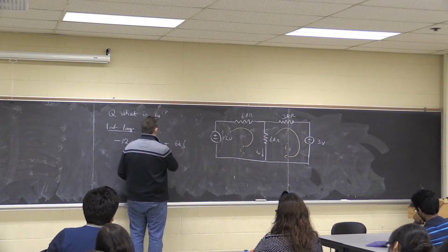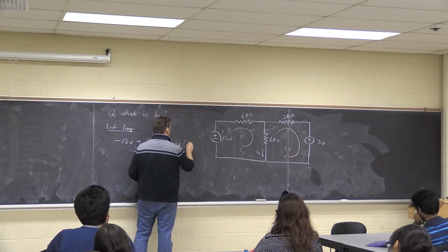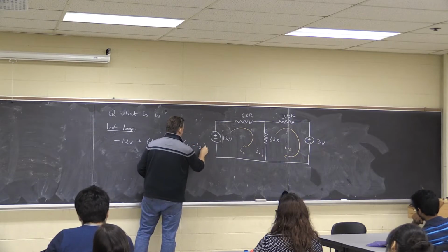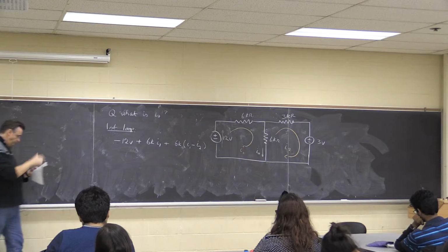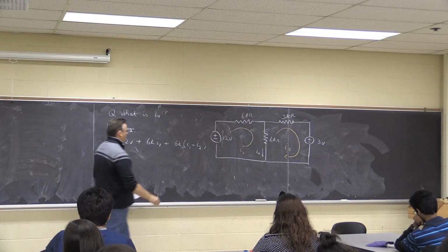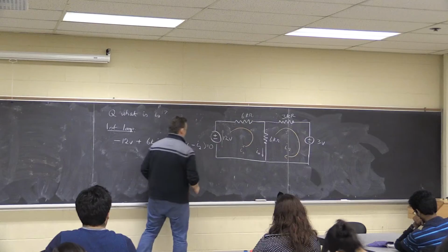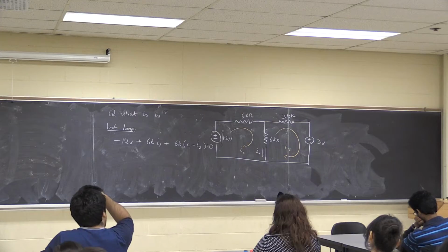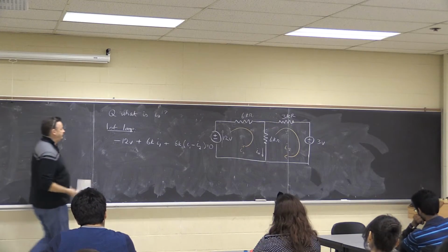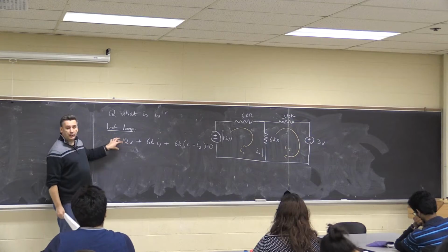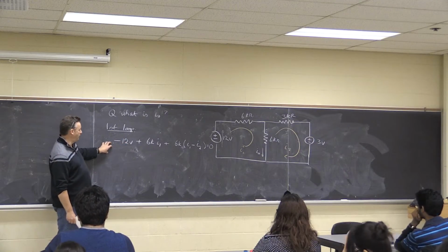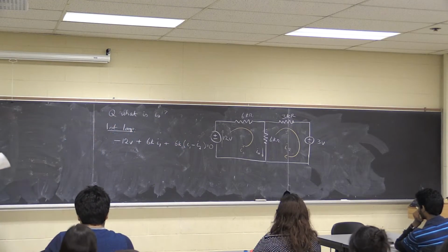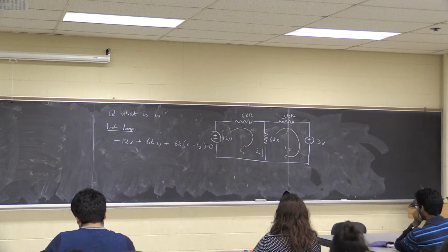So that would say that the voltage across that arm would be 6K times (I1 minus I2). And I know all that equals 0 because I've walked around the loop and got back to the other end. So all the potential increases and potential decreases have averaged out. If you want to say on one side the voltage increase is 12 volts and that equals all these voltage drops, you'd have the same equation. And you can see that if I just take the minus 12 to the other side.